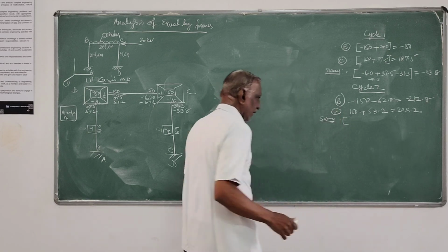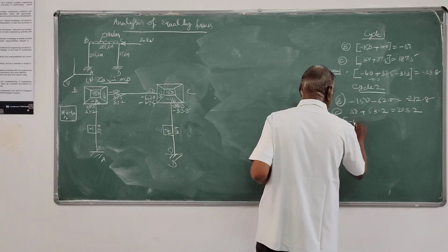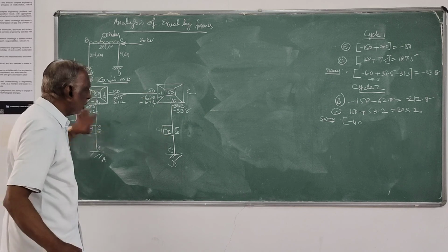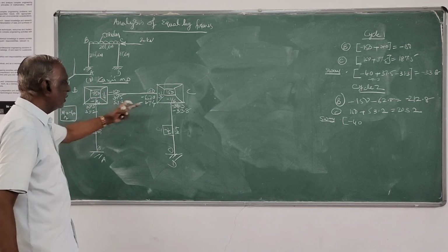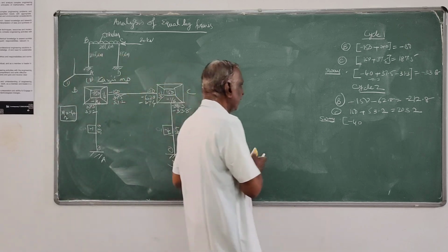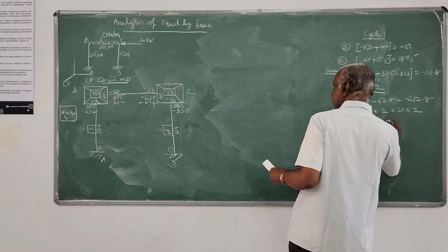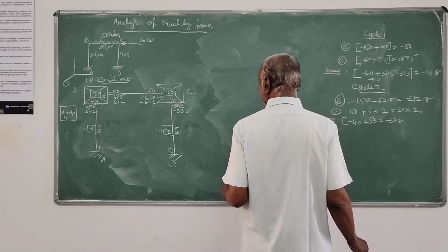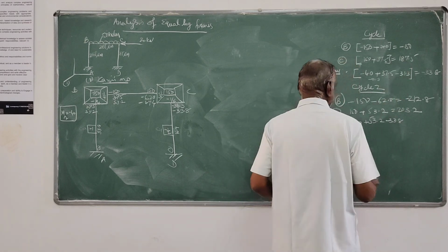So again first the sway moment MR, that is minus 40 plus the rotation contribution at the ends of all the column members, that is 53.2 plus 0 minus 33.8 plus 0, that is 53.2 minus 33.8. Oh, here I forgot to take that minus 20.